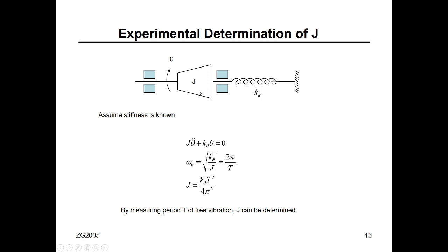We did this in the lab. If you have a mechanical system and you're looking for the mass or the spring, either one of these you don't know. In the lab, we have an unknown spring and a known mass. Here, the opposite. We have an unknown mass, like a turbine, and a known stiffness, like the stiffness of the rotor shaft.